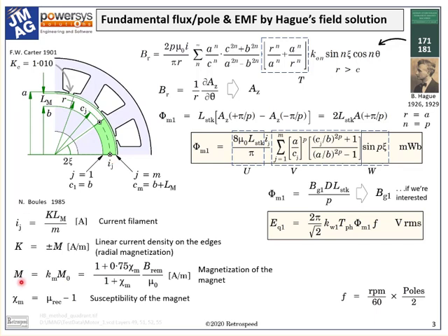M is the magnetization. Boulez modified this magnetization to allow for the recoil permeability of the magnet, and his adjustment, K subscript M, is typically of the order of 0.98 to 0.99. Boulez actually integrated the field solution equation with respect to R along the magnet edges, but here we are going to use 10 intervals giving 11 filaments IJ and add them all together.